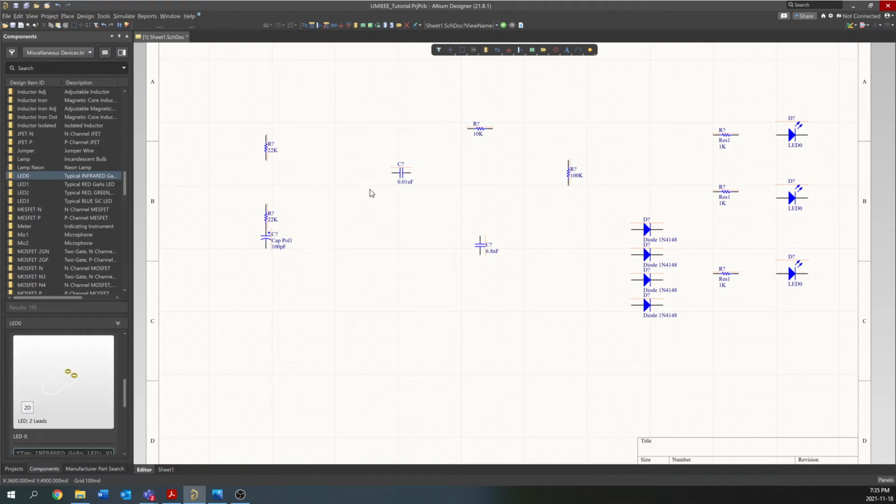You can, so that is based on the footprint. Generally, no. What gets printed on the PCB is the designator R39, C27, whatever. Then you have to go back to your schematic and reference your schematic. Control F the PDF to find whichever component you're looking for, and then double check what size value. You could print it, but it would take up so much room that I think generally that's not a typical design practice.